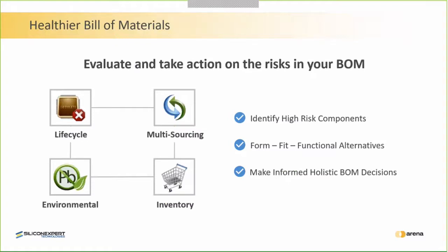For starters, the component product lifecycle is a key indicator. What is the lifecycle status of each device? Has a component recently moved to not recommended for new design? Even more critical, has it gone obsolete, and was this obsolescence notice delivered in time for you to make informed decisions before that device is no longer available? Inventory